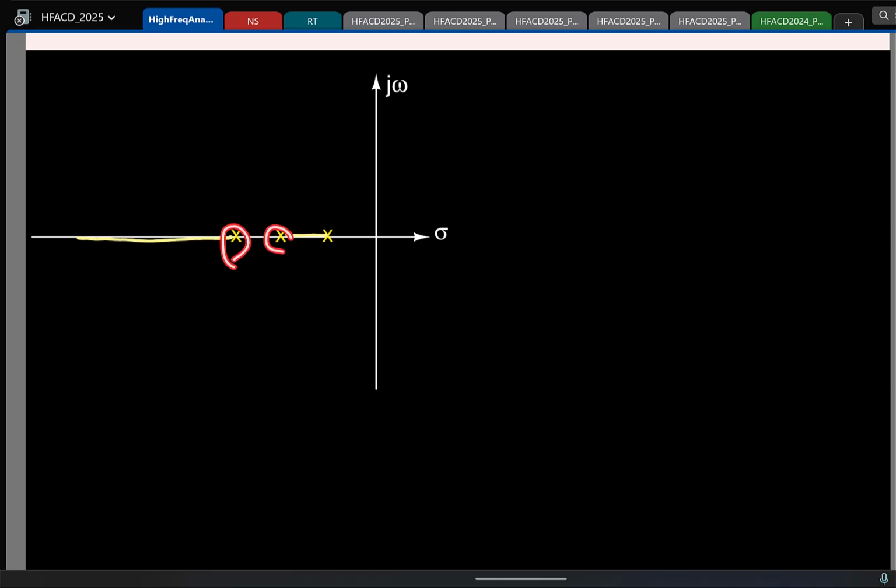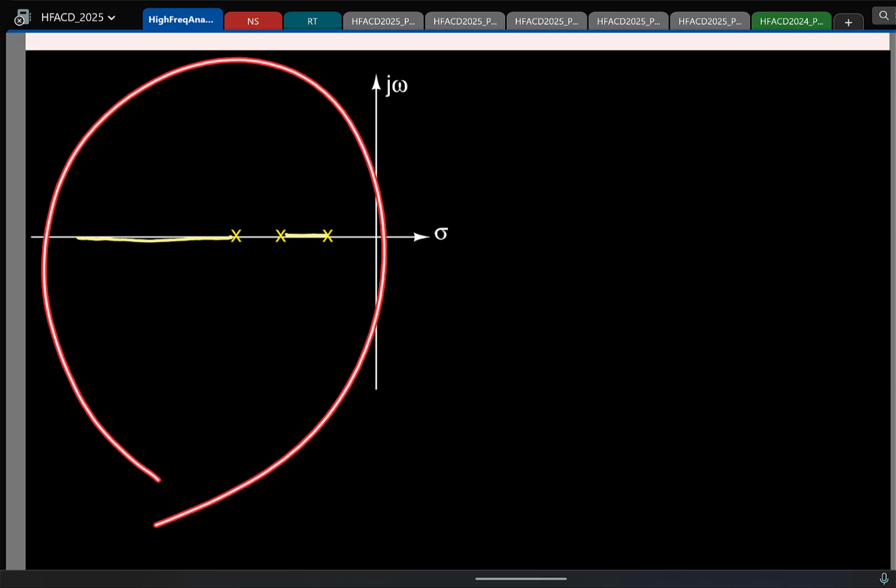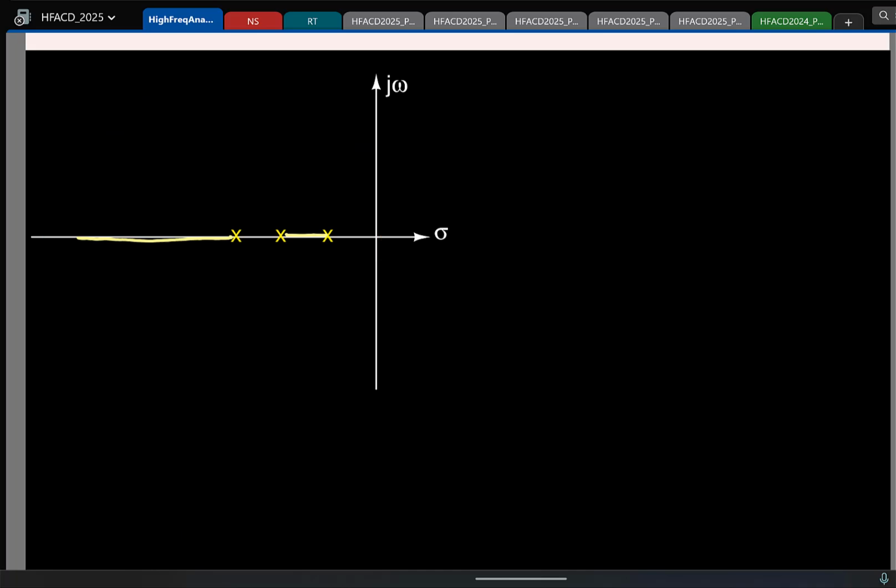Now again, I have 3 poles. They have to go to infinity. I have 360 degrees of the S-plane. So I have 3 of them. How will it get split? 360 by 3, 120, 120, 120. I mean, simple land division problem. We have a land divided amongst 3 siblings. To be fair, you share it equally. So one of them will take this, other will take this, other will take this. So you have 120, 120 and 120.